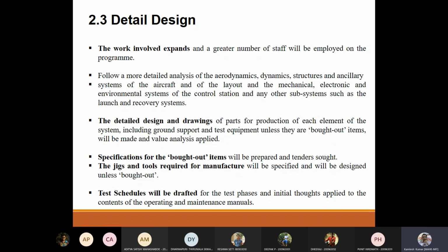That is not perfect, because people are putting lots of antennas and lots of equipment looking externally, correct, which may not suit the aerodynamics. Now people are talking about stealth design, which is not possible if you go 100% aerodynamics. So that is the compromise. It means you should have a very detailed analysis of the aerodynamics. Either you compromise the aerodynamics as per the design or feature requirements, or you look at all those features so your aerodynamics can be 100%, correct? So this is the gap.